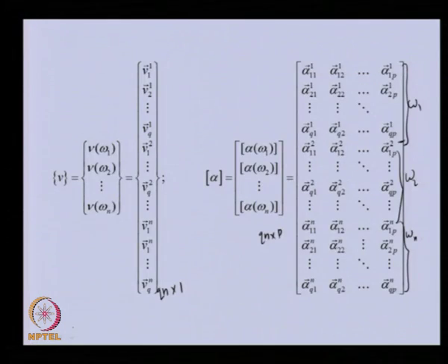Now, you can see, you will go back to the previous equation, this equation. So, basically here V, that is W1, corresponding to this, these are the displacements, and corresponding to this, these are the influence coefficients, and this influence coefficient is the same as in the subsequent equation I showed. We expect that when we are keeping the trial mass, these influence coefficients will not change.